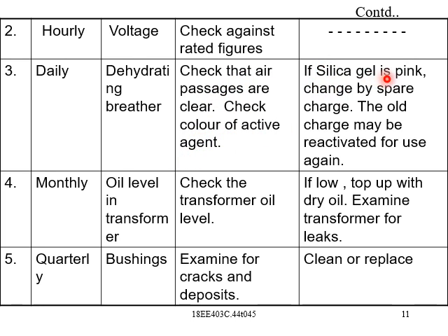And if the silica gel is pink, change by spare charge; the old charge may be reactivated for use again. So one action to be done: if the silica gel is pink, actually blue color, pink, and if it is totally damaged, it turns pale yellow. So if the silica gel is pink, change by spare charge; the old charge may be reactivated for use again. It may be used again.